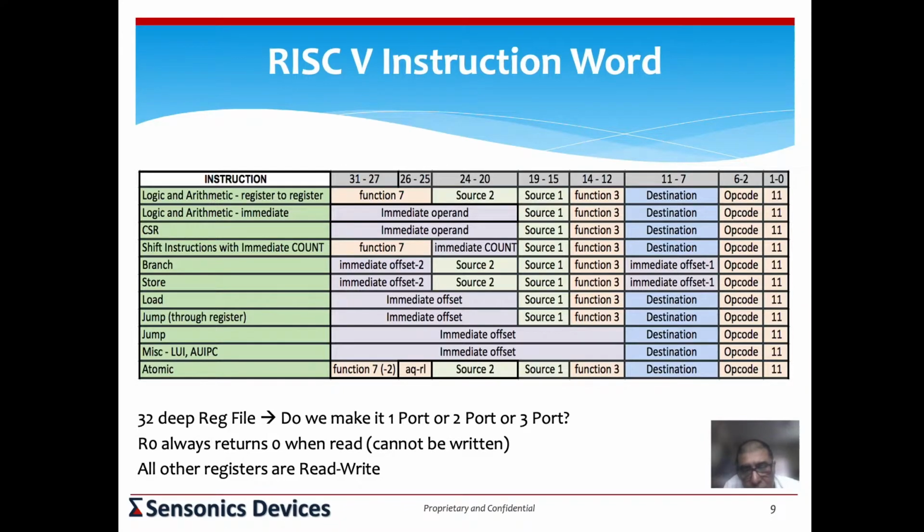And as you go along the design process, you can actually change those decisions. If you made one to start with and you go along the process, and then as you move along and start writing flowcharts, you will realize that there is a piece of hardware that you need to put. You stop the work there, build that piece of hardware, push it into your data path in a drawing, and then look at that to write your register transfers.